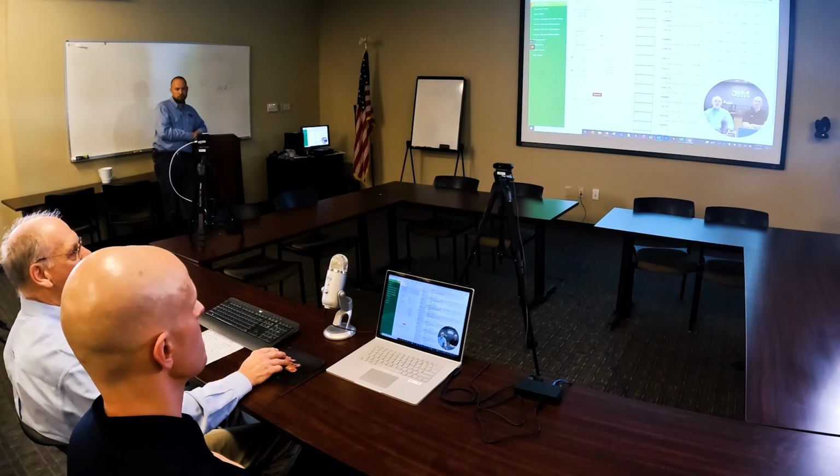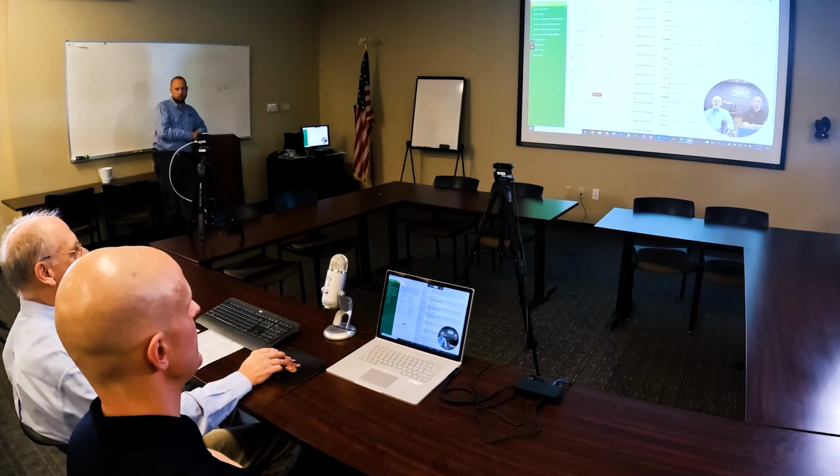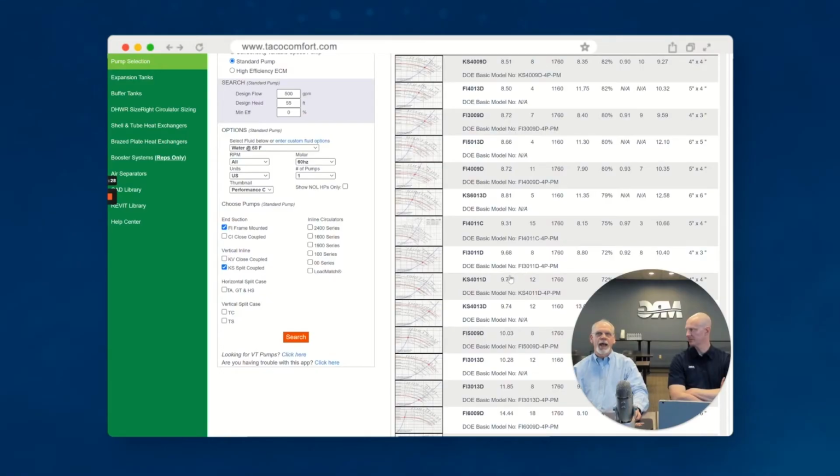That's correct. You need to have that pump cavity full of water at all times. We do have some pumps at times I've seen where they will collect air in the top of the pump on the horizontal split case pumps. And if you have air in the pump, it's not going to pump water. Yeah. And so that can give you a very bad situation with that. If it is not determined that that's what the problem is and there's no one there to check things, you can boil the water out of the pump and create steam in the pump because you're not moving the water.